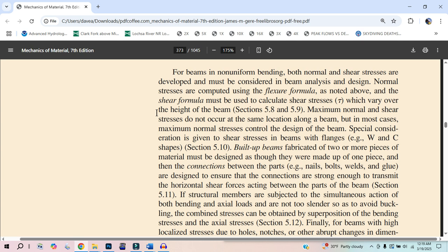Let's say it's a 1/4 inch hollow steel tube, to make the analogy more impressive. Now I can apply two opposing forces at an eighth of an inch from the centers. The moment is going to be that total distance, a quarter inch, times one of the opposing forces. Anyway, it's kind of just the definition of a couple.